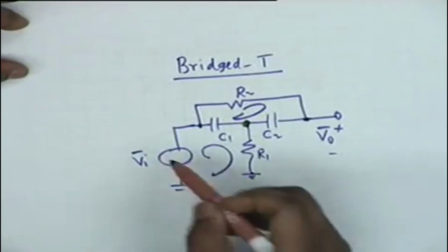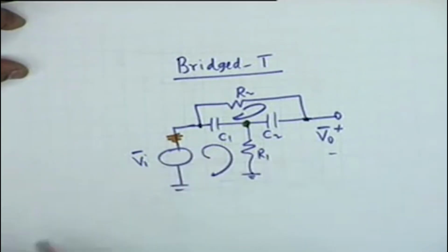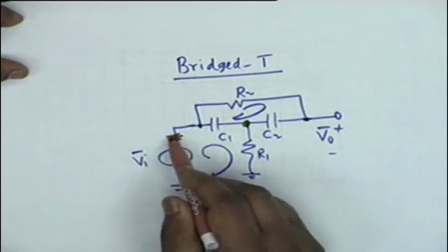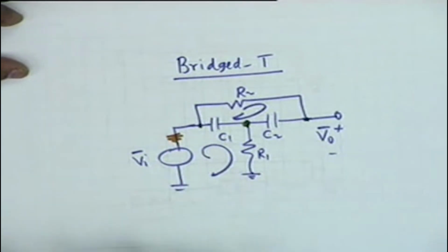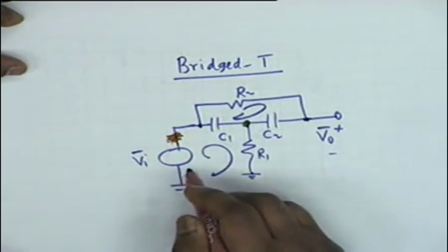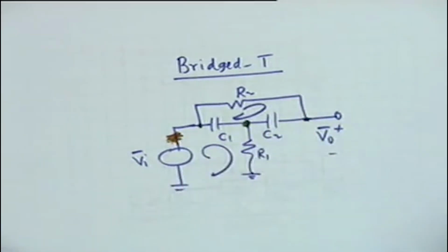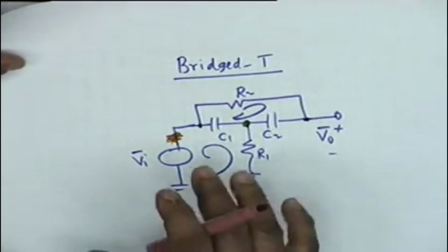because you might fall in a trap. This does not apply if you have internal resistance here. If there is an internal resistance here, then this method of analysis fails. Not only that, if instead of a voltage source it is a current source, it does not apply. Only in terms of an ideal voltage source, you can separate the two branches and connect two identical voltage sources. Alright, wherever a situation like this occurs, this allows immense simplification.